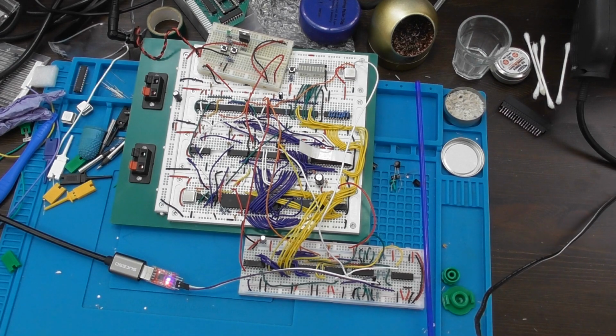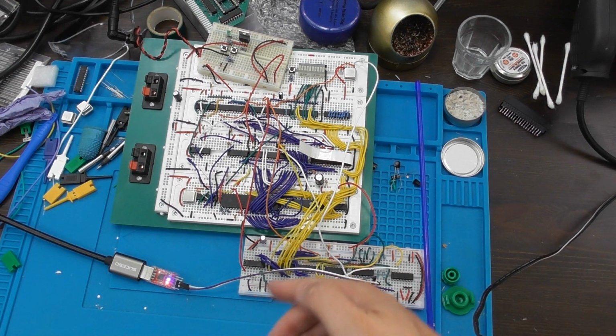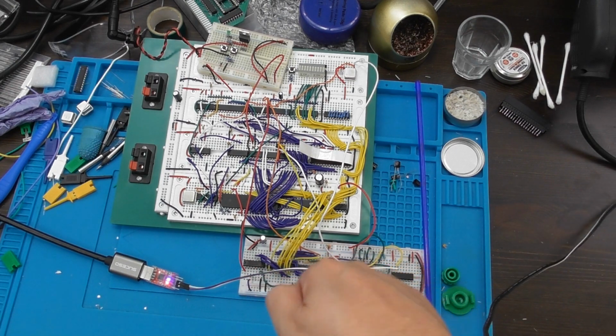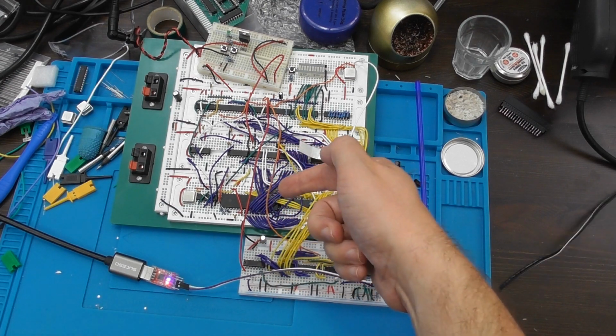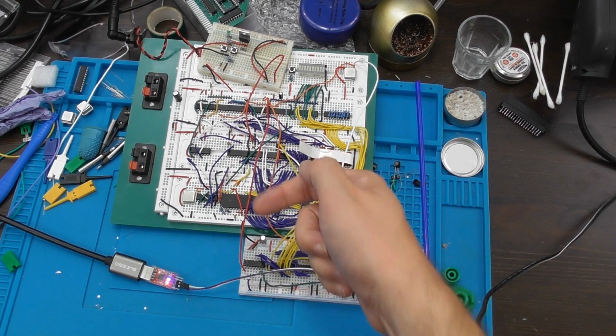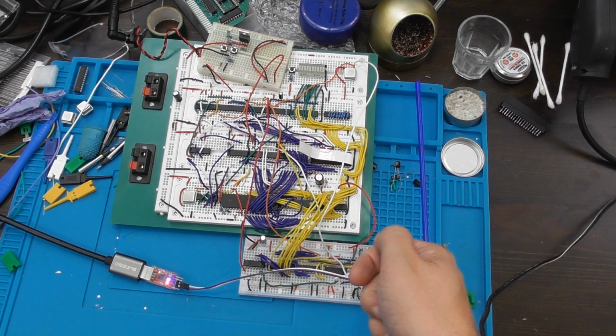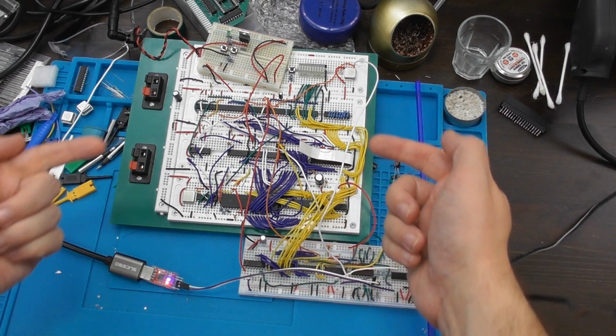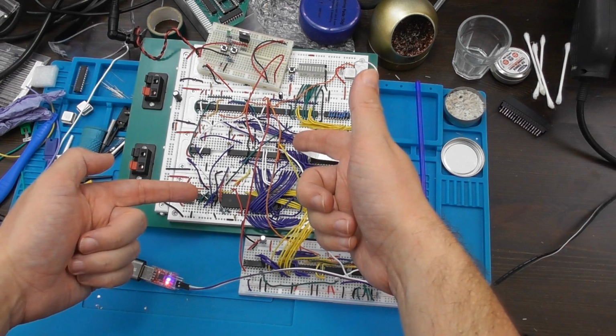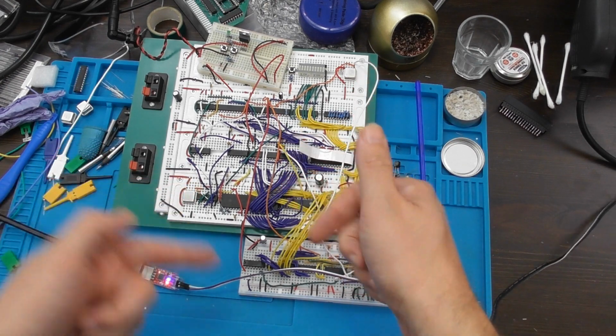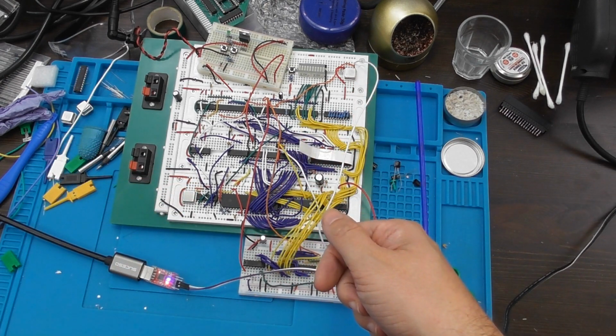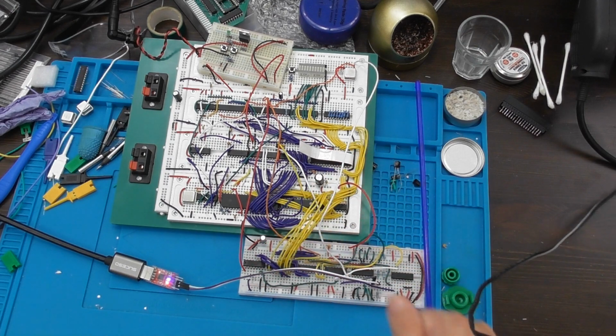And in addition to all of that, I'm going to set up an interrupt output from this circuit so that it can interrupt the CPU whenever a character arrives on the read circuit, and also after transmitting a character on the transmit circuit, because that'll allow us to write asynchronous code on the computer to automatically send characters and receive characters when they're available into buffers in memory. So with all that said, let's have a look at the schematic for the receive circuit.